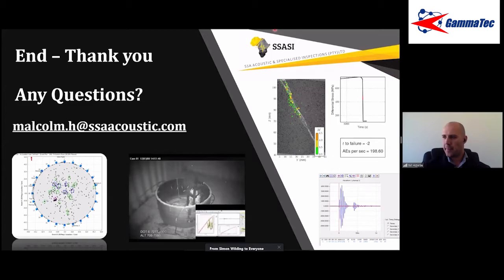Now here, we can work around this by acoustically coupling the sensors via just a long rod with a sensor on the end, which is then welded to the structure. Now this standoff reduces the temperature to a manageable rate, but it still leaves acoustic coupling. We do reduce sensitivity, but you are able to do it. So this is quite often used in high temperature pipelines that may have a crack that has been clamped. We would then weld a few of these waveguides on, attach the sensors, and monitor the crack or area of repair for any further crack propagation during startup especially, and in service.